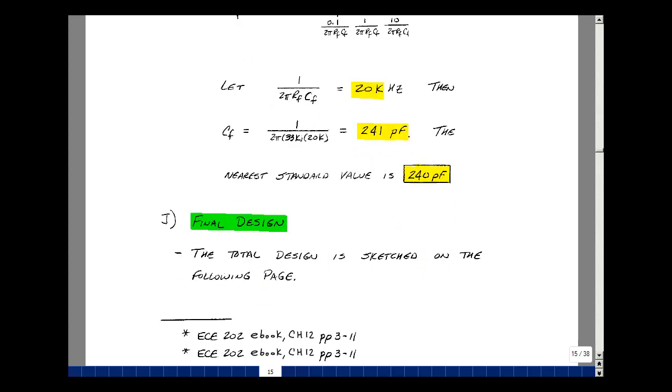Here's our entire system drawn out. We start out with the output from the microphone on the right and left channel. It comes in through a capacitor, which blocks the DC, both of these. It sees a fairly high input resistance compared to this, so we don't see much loading effect. Then we have the gain of 1 plus the resistor ratio when the frequency is high enough to make this a short circuit. Of course, the same thing's happening on the left channel.